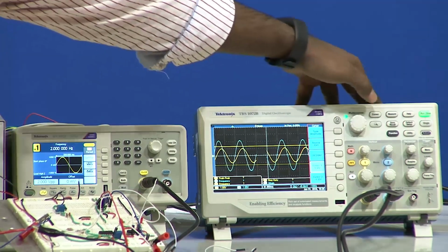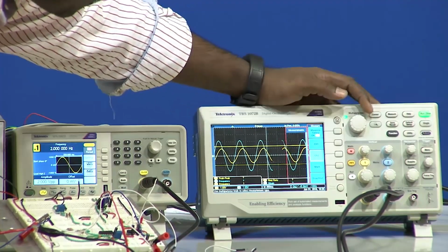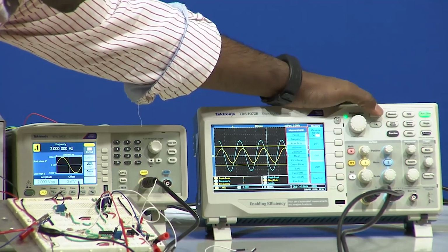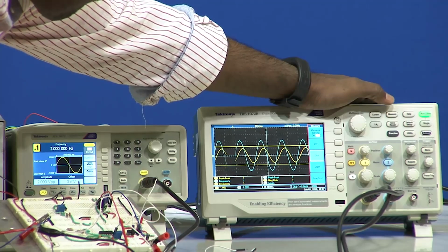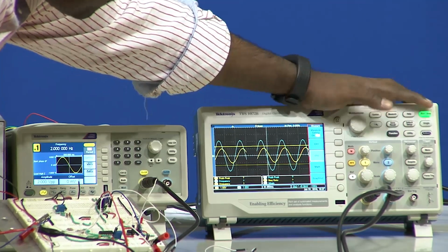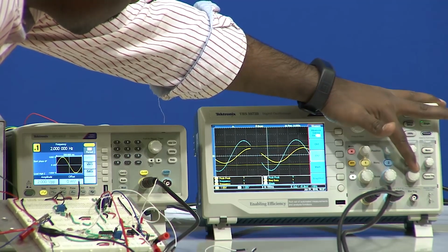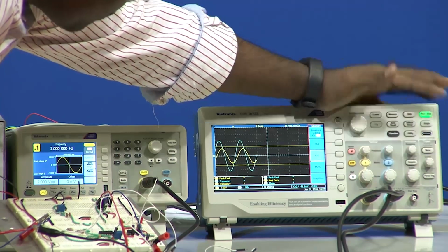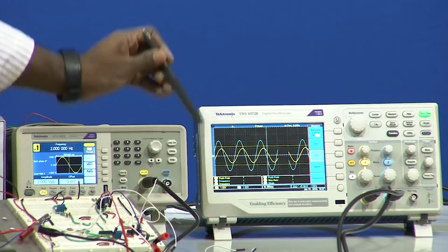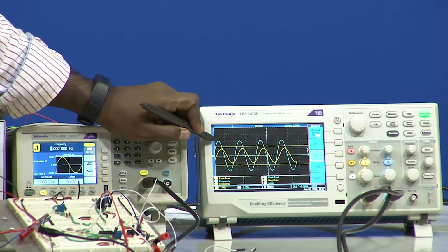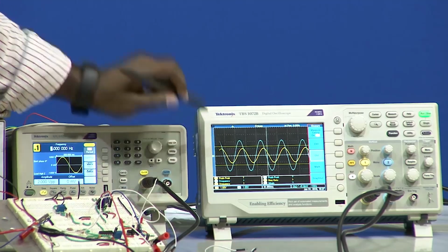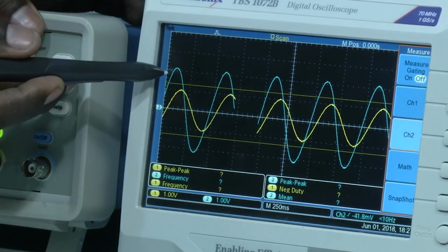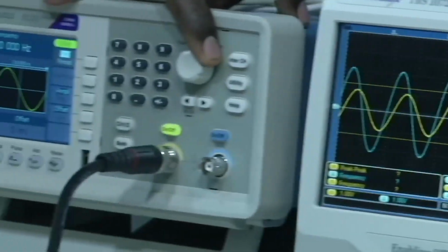Here if I observe, I will go to measure and create a channel 2 peak to peak value. From the peak to peak value we can easily understand. Sorry, this is unable to measure, but that is fine, we can see that the output value, the blue color one, is slightly higher than this second box. That means the gain is increasing. Now, I am coming to 1.